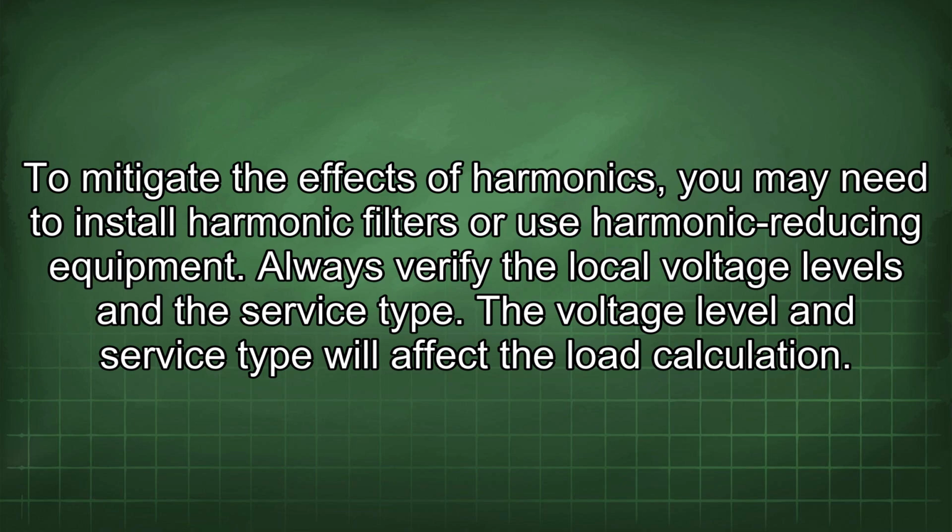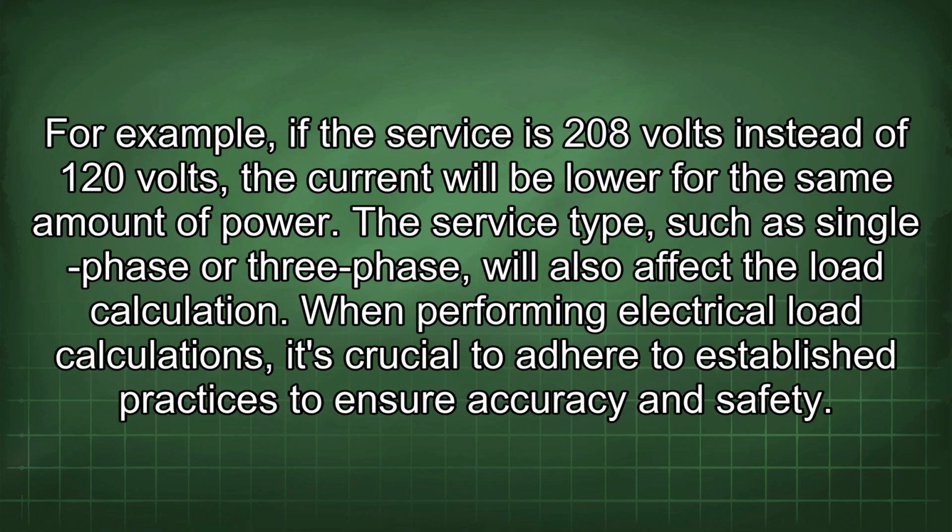Always verify the local voltage levels and the service type. The voltage level and service type will affect the load calculation. For example, if the service is 208 volts instead of 120 volts, the current will be lower for the same amount of power. The service type, such as single-phase or three-phase, will also affect the load calculation.